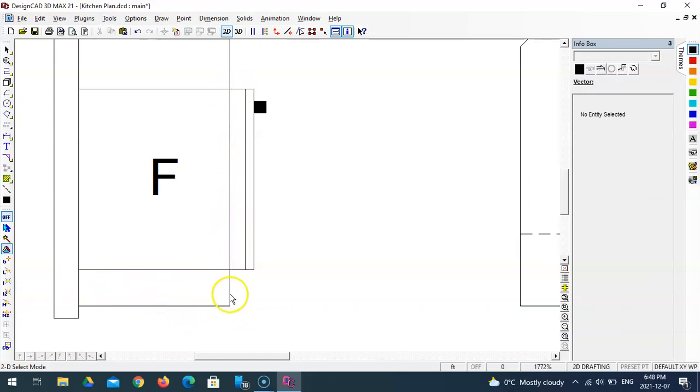Well, that's not good. Let's get rid of that line simply by getting my extension tool, which is under my trim tools, and right clicking. Actually, I'm going to left click here because when you right click, you never know which line it's going to get. So see, when I right click, it is getting the right line, but it might select this one. So I can left click, then pull this up, and then right click.